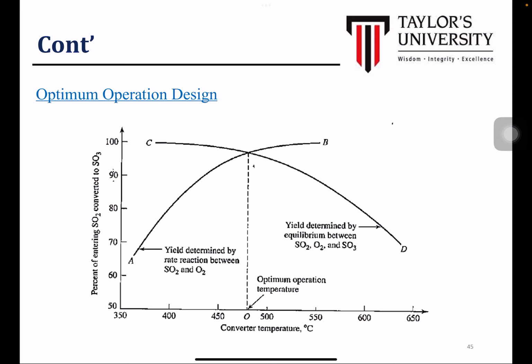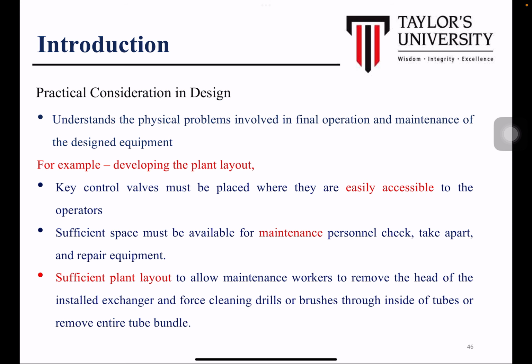Alright, you can also compare the processes in terms of the yield or selectivity as well. So there are many optimization tools based on various variables that can also be performed. You can also do it in Aspen HYSYS. You can do some optimization or sensitivity analysis where you can observe how changing a parameter affects your process. How does it affect your product yield or maybe the purity and so on. So perform some optimizations.